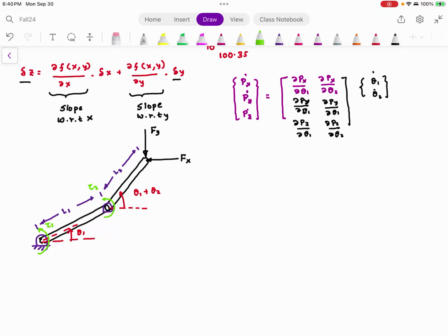So there is Fy and there is Fx. And how much torque do I need to supply at these joints so that I can support that end effector load? Everyone understood this? In the previous problem, I was interested in the motion, the movement. I wanted to find out how to relate the joint velocities with the end effector velocities. Here I want to find out the joint torques so that the end effector weight is supported. Do you guys agree with me?